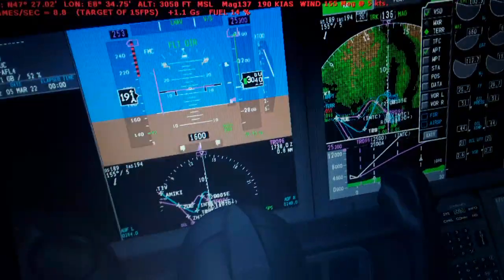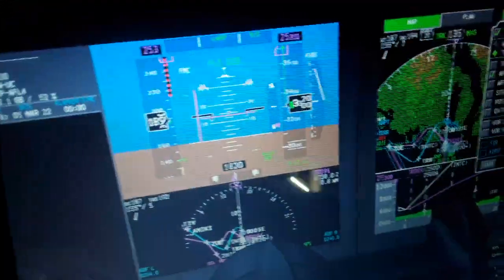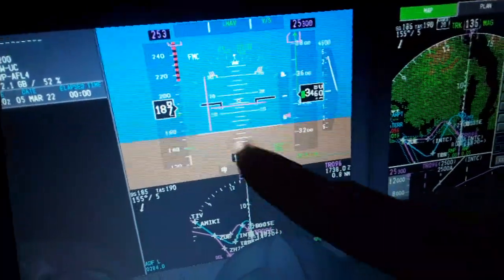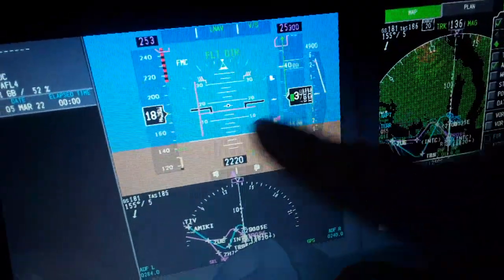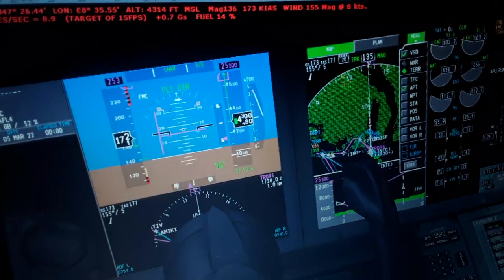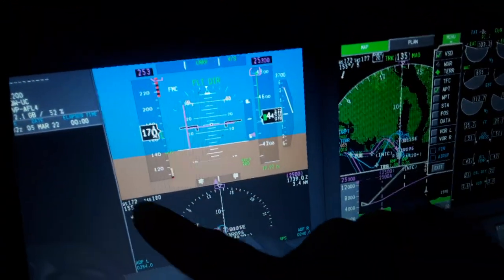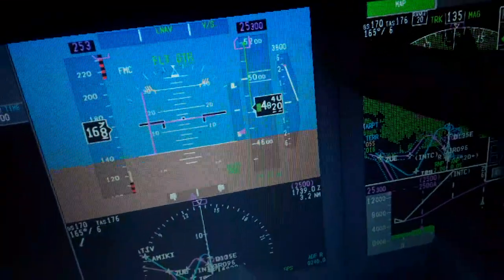So here we are 1,600 feet above the ground, 1,800, 1,900, 2,000 feet above the ground, about 3,600 above the sea. The airspeed 180 knots, the stall speed red and yellow here 120 knots, we'll decrease the pitch attitude to less than 20 degrees. The wind direction and speed now, also the terrain around you and below you. You can see the trend of the climb over here.